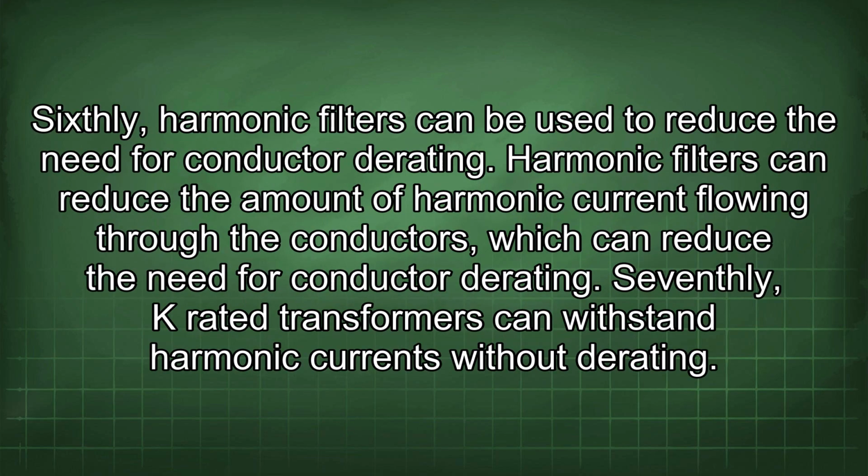Sixthly, harmonic filters can be used to reduce the need for conductor derating. Harmonic filters can reduce the amount of harmonic current flowing through the conductors, which can reduce the need for conductor derating. Seventhly, K-rated transformers can withstand harmonic currents without derating.